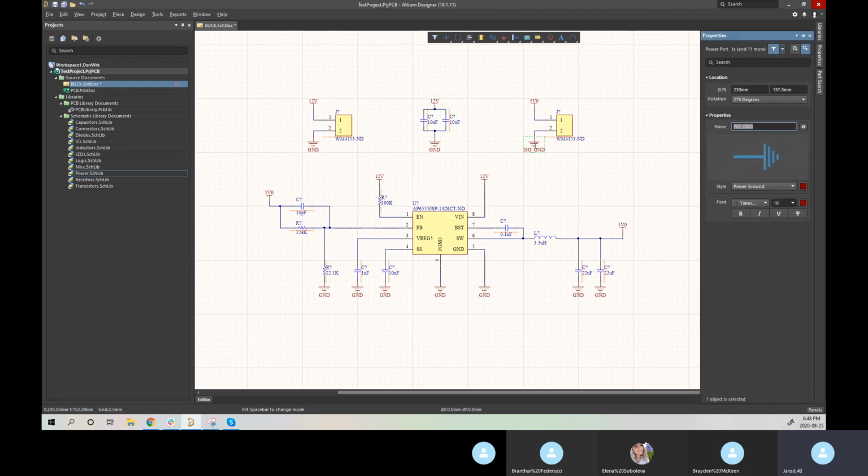So when we're dealing with high voltage systems, or systems where we want that isolation between high voltage and low voltage, or just the grounds in general, for whatever purpose it may be, you want to make sure you change one of your, or both of your, ground names.